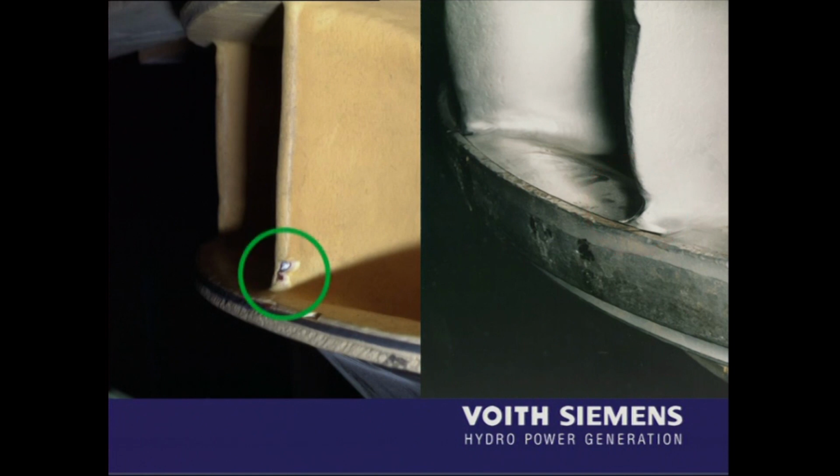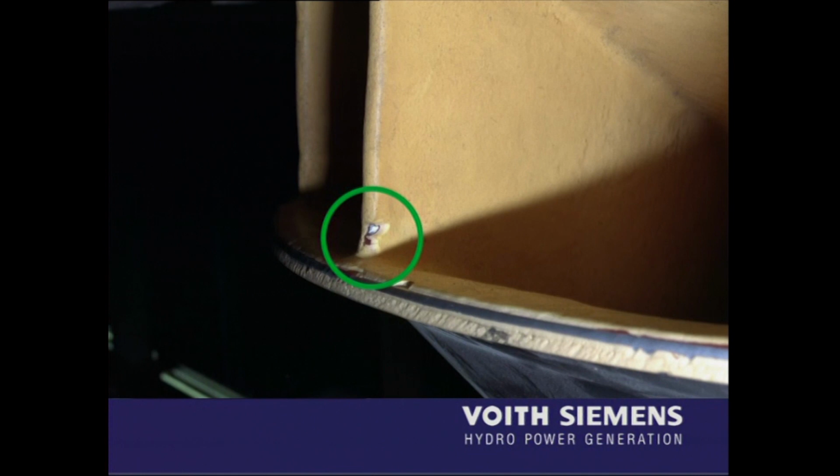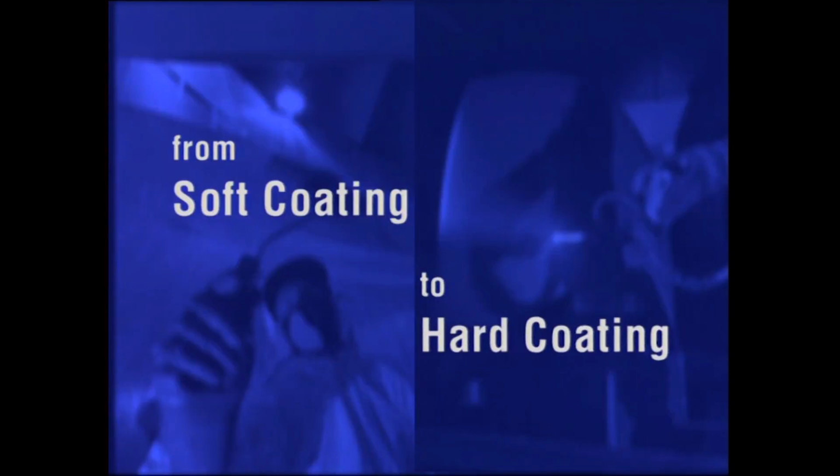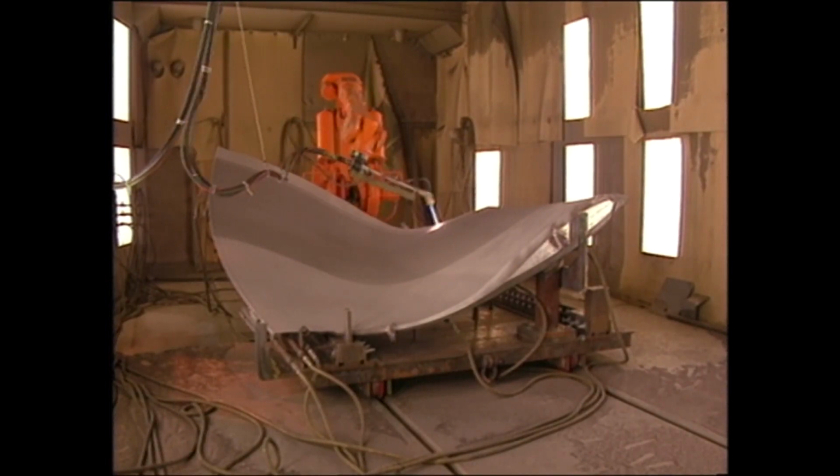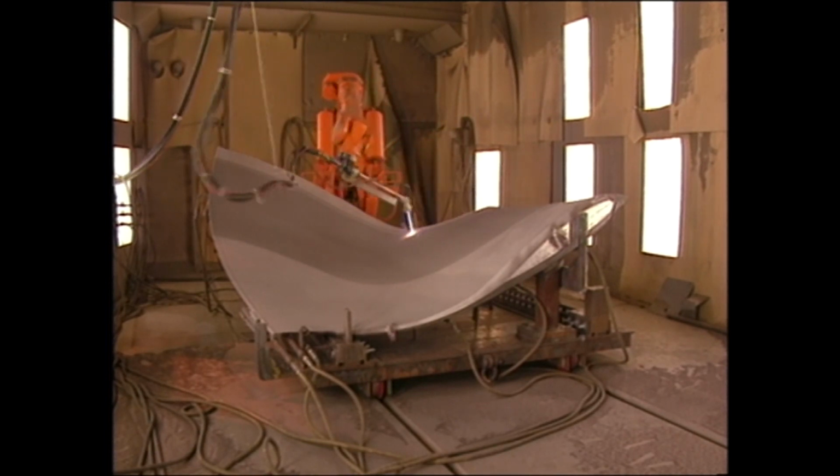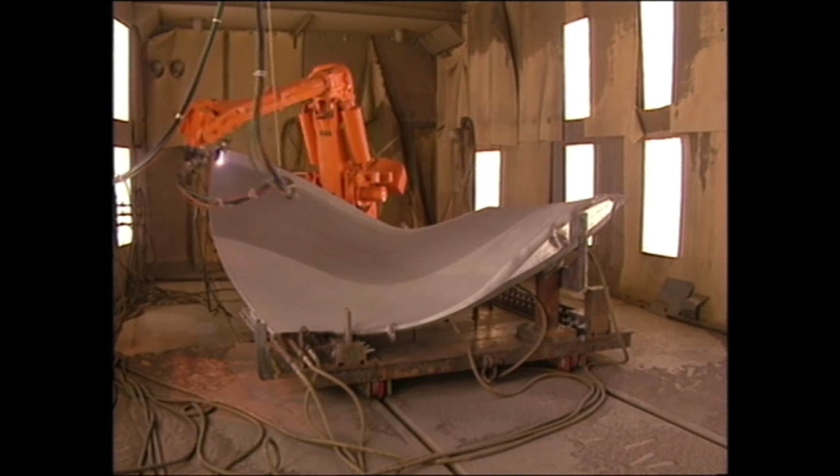The soft coating has only slight local damage, which will not cause any further problems, owing to the excellent repairability of the material. Regarding the application process, soft coatings depend mainly on craftsmanship. HVOF sprayed hard coating, in contrast, requires a high level of control and sophisticated technology.